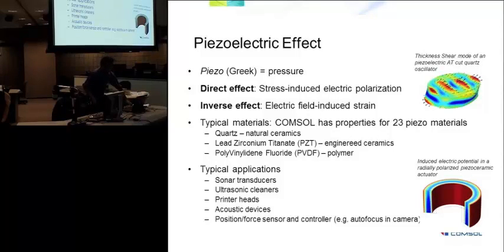So start with the piezoelectric effect, which seems to be another important field in MEMS modeling. Piezoelectric effect, piezo means pressure, and it's found in piezoelectric crystals. The effect basically means either you apply a mechanical load and convert it to electrical charge or voltage distribution, or you apply an electrical potential difference and convert it to mechanical stresses within the piezoelectric crystal. They are called direct effect and inverse effect.